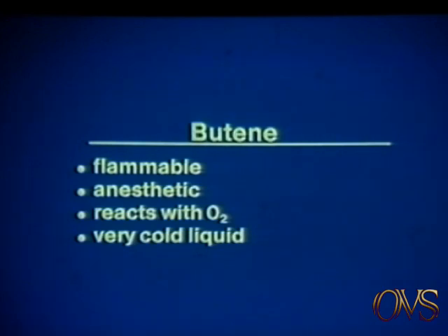Although colorless and odorless, high concentrations of the gas may cause an anesthetic effect. Basically, your body becomes numb. Wear protective goggles and gloves to keep from contact with the very cold liquefied compressed gas. If ventilation is poor, wear SCBA.